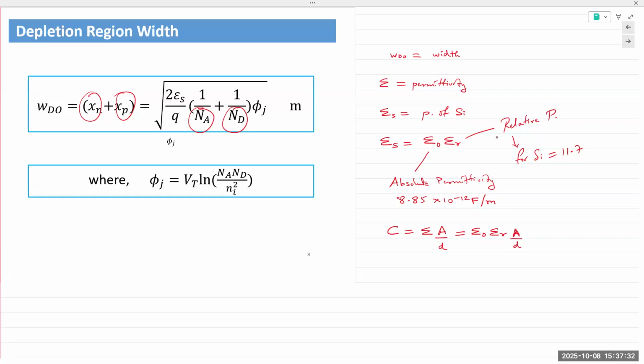Varactor diodes. Okay. So again, because there is charge that is stored in that junction, we can model it as a capacitance. It has a technical name. It is known as the junction capacitance. If we simulate this in SPICE, it is known as CJ or CJ0. It's one of the parameters we can specify in SPICE. Okay. And that's why it appears in that equation.